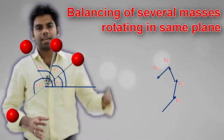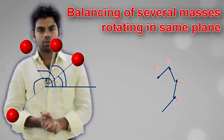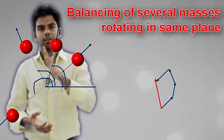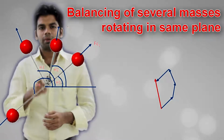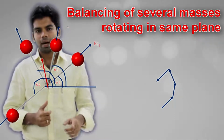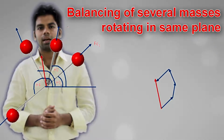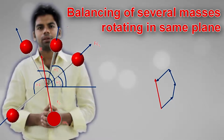Now the remaining side of the polygon will give us the resultant of the unbalanced forces. We will put this resultant here. So in order to balance this unbalanced force Fc, we will put a mass mb at a radius rb diagonally opposite to this particular vector.